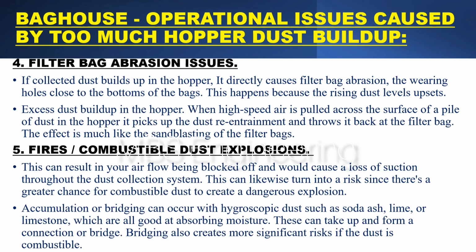Accumulation or bridging can occur with hygroscopic dust such as soda ash, lime, or limestone, which are all good at absorbing moisture. These can take up moisture and form a connection or bridge. Bridging also creates more significant risks if the dust is combustible.